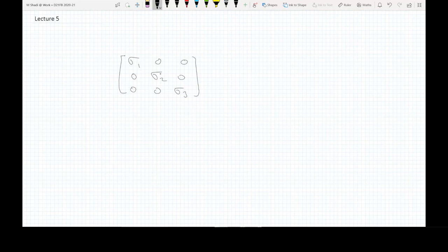Now, on the plane, basically the planes for them are going to be N1, N2, and N3, probably just write them as vectors. So N1 is the plane where sigma 1 will exist, sigma 2 will exist on N2, and sigma 3 would exist on N3. So these are the maximum normal stresses. On these maximum normal stress planes, you don't have any shear stress. However, there exists some maximum shear stresses that live on a different plane.